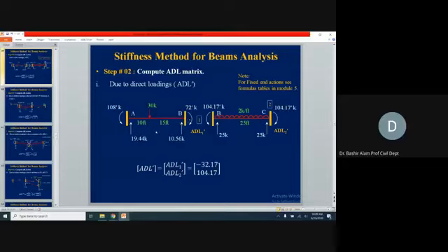But now the unbalanced moment we need to balance. So how are we going to balance? If you see here, 108 is more than 72. So we need to balance this counterclockwise with the clockwise couple. So whatever reaction comes here will be upward directed. So it will be plus, upward means it will be adding with this 18 we already found.